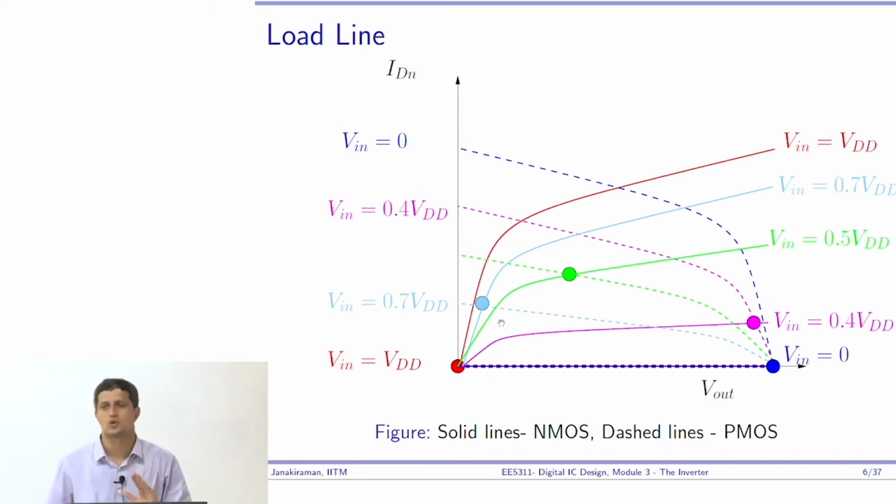So as I told you, if there is leakage current, then this exact 0 and VDD will not happen. There has to be some current through the NMOS transistor, so the PMOS will adjust the VDS so that that amount of current is allowed through the NMOS transistor when Vin equal to 0. So then it will be slightly above 0, but it will be negligibly above 0.